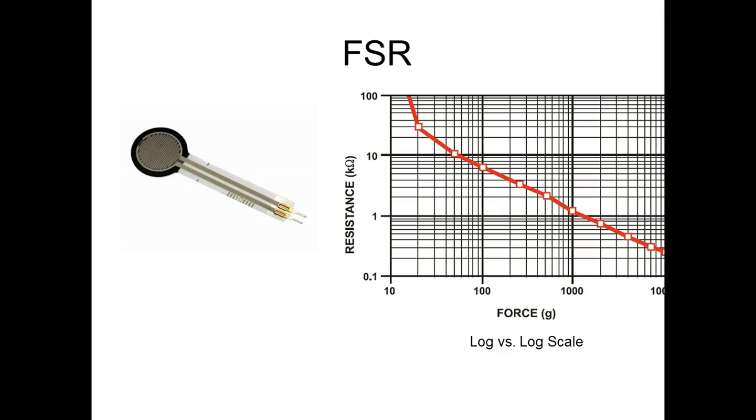So it varies its resistance. Odds are we would hook this up into some type of circuit that's got a threshold on it, like we showed you a while ago. If I actually wanted to get a weight out of it, then I would use a Wheatstone bridge, right? Are we okay? Questions?